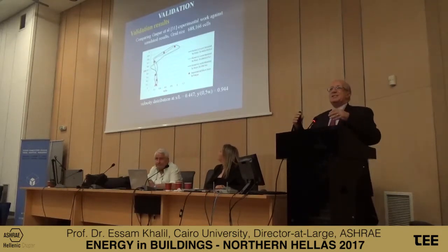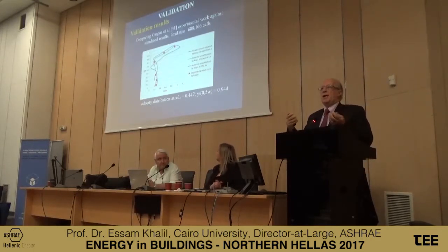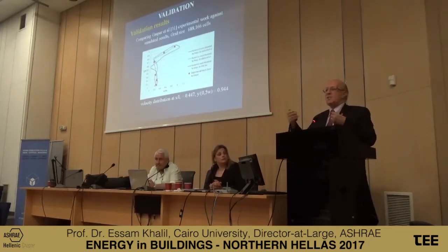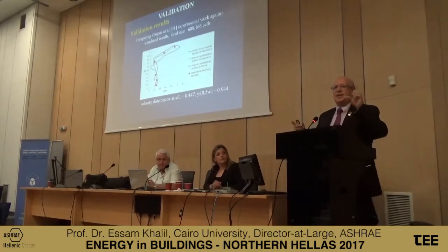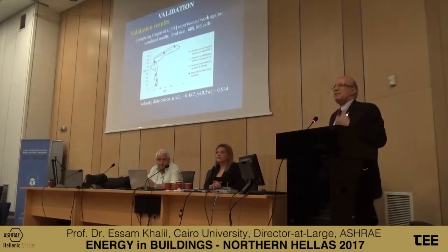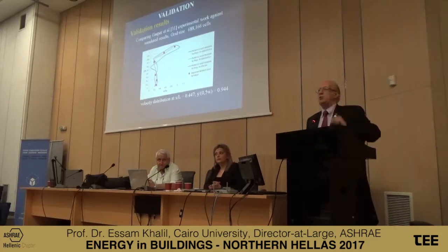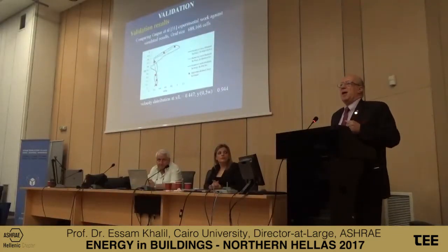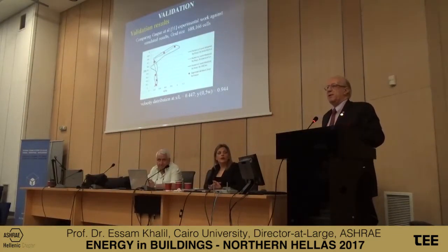A turbulence model is a model that assumes the flow behaves in a certain way and calculates the viscosity or the shear stress based on two parameters, in this case the kinetic energy of turbulence, K, and its dissipation rate, epsilon. So it is a very famous two-equation turbulence model that was proposed by Imperial College back in 1972. It's still alive till now.